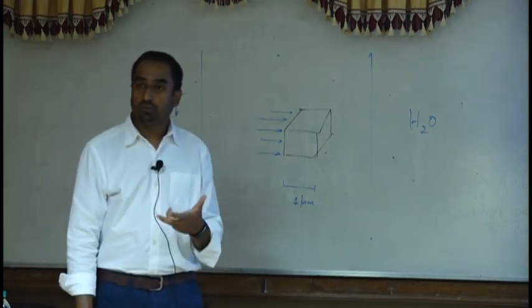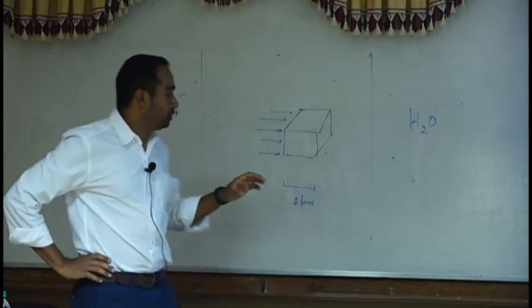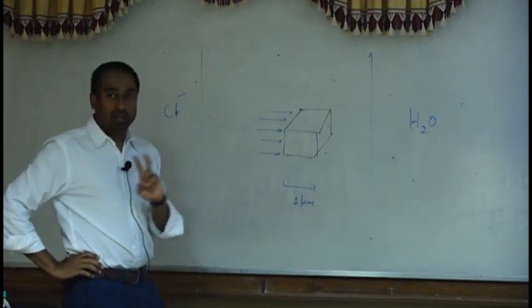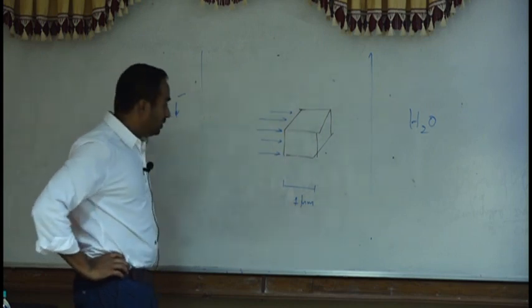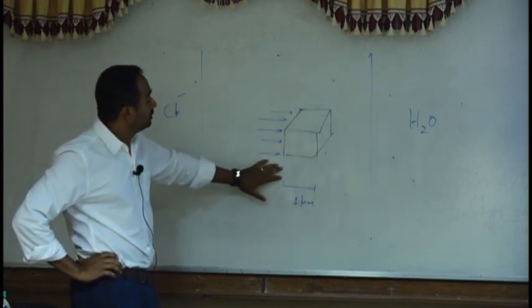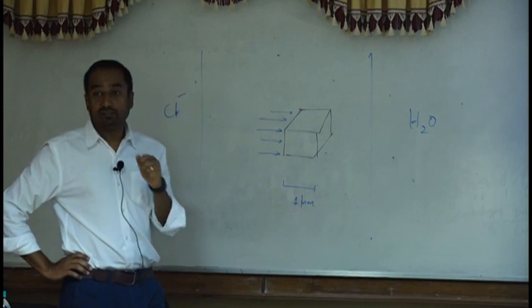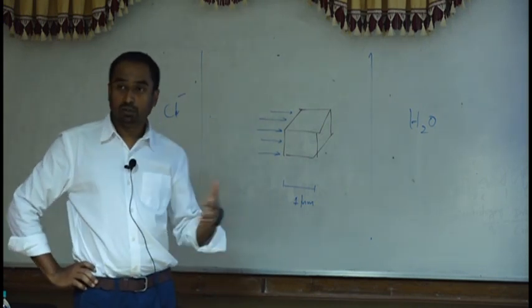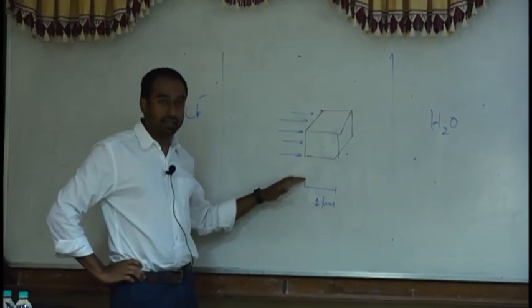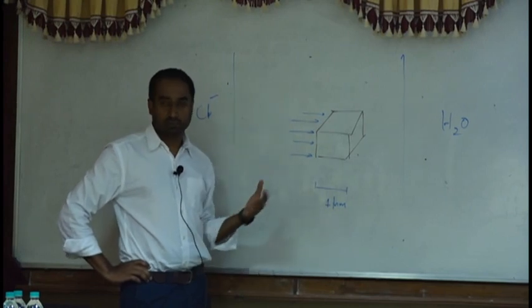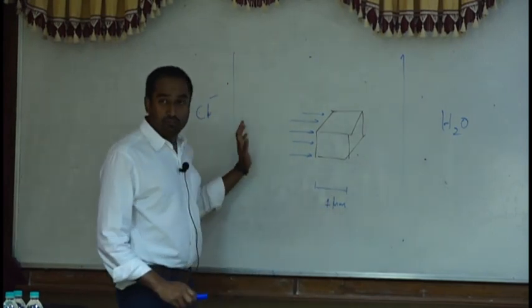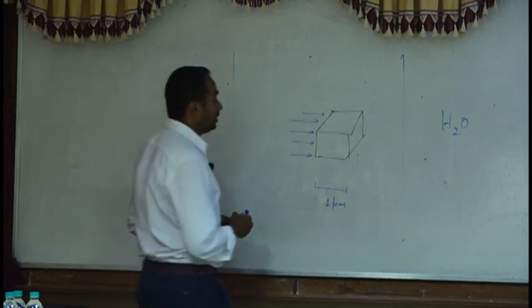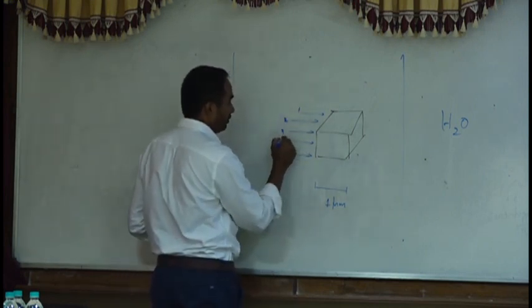The movement of chlorides or any other ion in concrete is a two-part equation. One is the transport, which is simply driven by the concentration gradient. And the second part is the reaction that it provides. Concrete is not an inert material, it's an active material. So it will react. So let's say there are 5 chloride ions going here. 1, 2, 3, 4, 5.